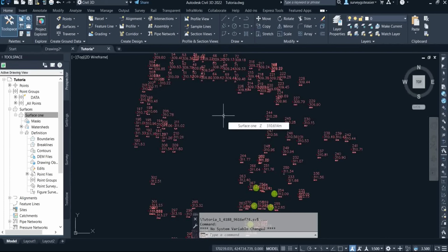That is, you are introducing points towards data you have before. You are adding more data to this. So for you to carry out interpolation on your Civil 3D environment, it's quite easy and straightforward. Of course, I'm still going to be sharing with you on working with spot height. Spot height is going to let you use interpolation as well. You can carry out spot height with interpolation, but we've not gotten to that place.